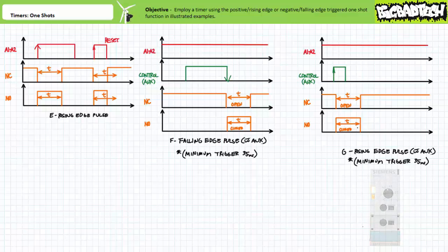Troubleshooters take note. A multifunction timer executing the right function at the wrong time needs to have the delay adjusted. In contrast, a multifunction timer executing the wrong function at the right time needs to have the function adjusted. I'd like to say a misinterpretation of functions is a rare occurrence, but it isn't, and you need to be